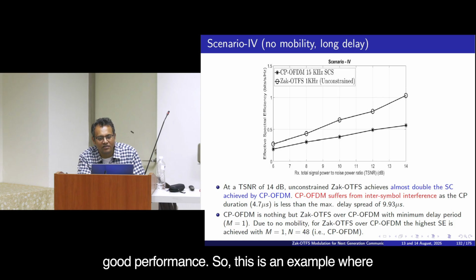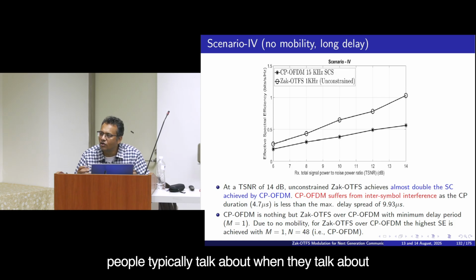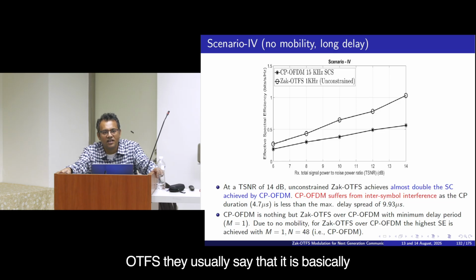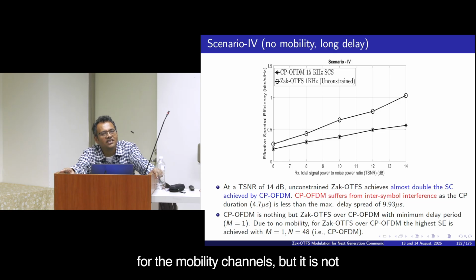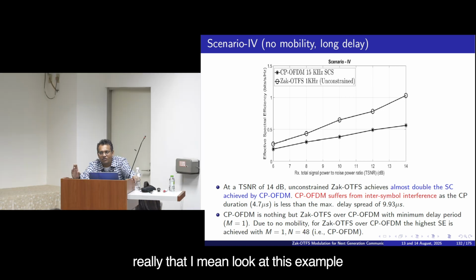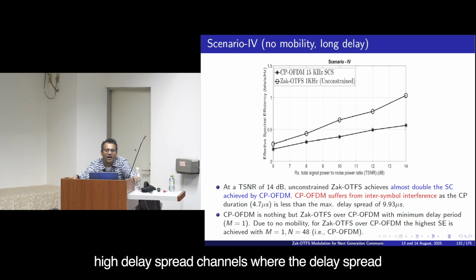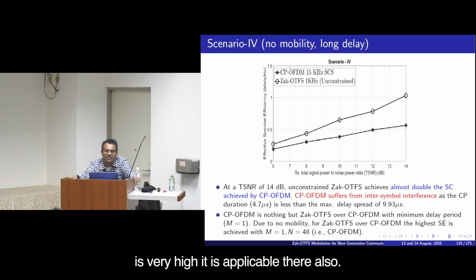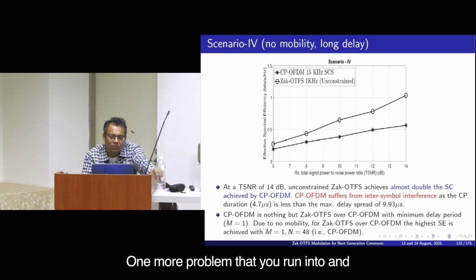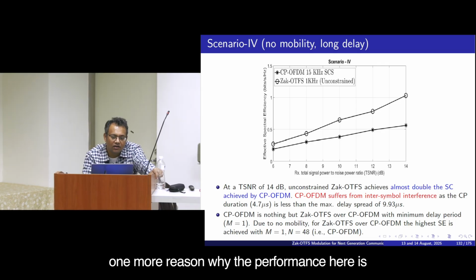very good performance. So this is an example where, when people talk about OTFS, they usually say that it's basically for the mobility channels, but it's not really that. I mean, look at this example here. It can also be used for high delay spread channels where the delay spread is very high. It's applicable there also.